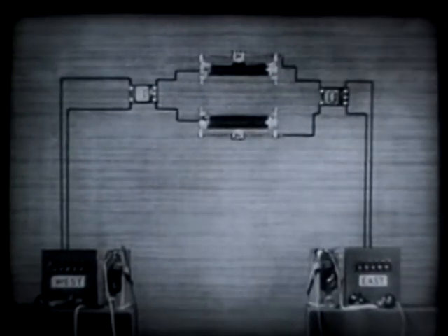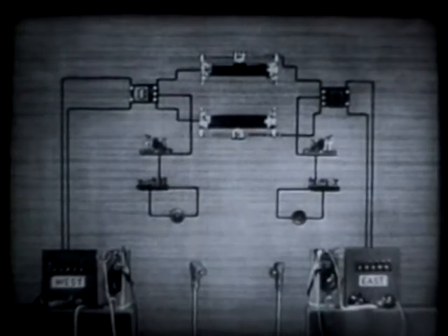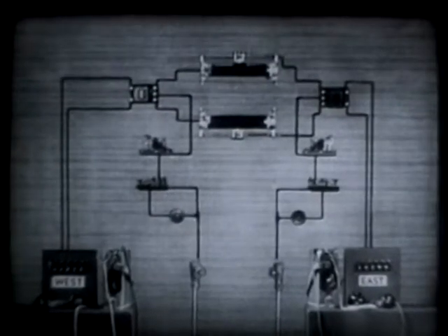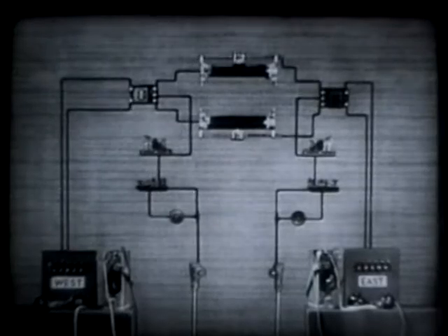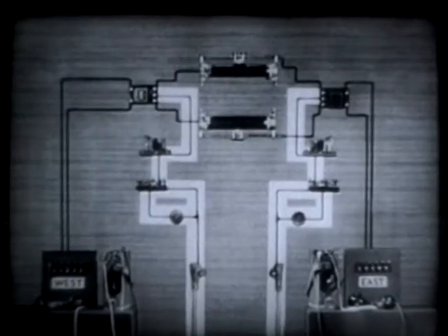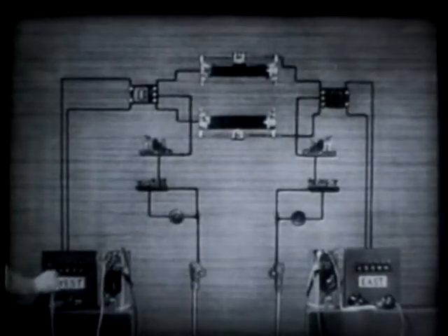Now we can connect a telegraph set to the midpoint of the line side winding of each repeating coil and complete the circuit through the earth. We have added the telegraph channel by using only a few extra feet of wire. The switchboards can still signal each other.